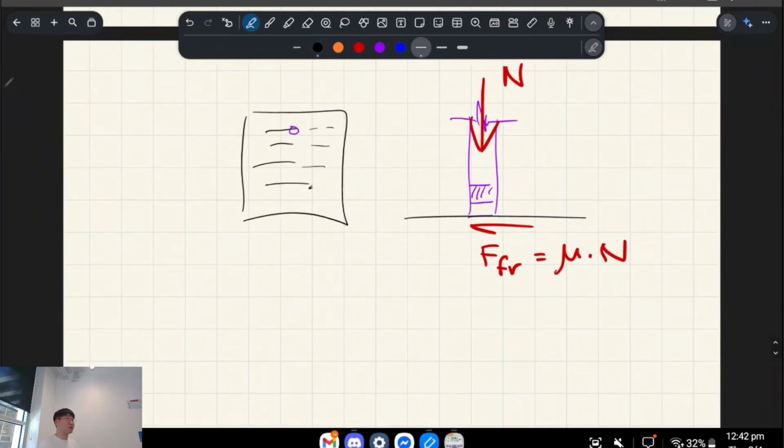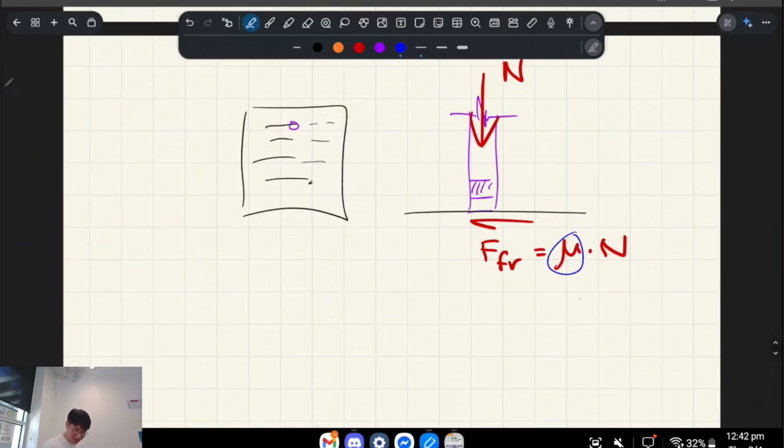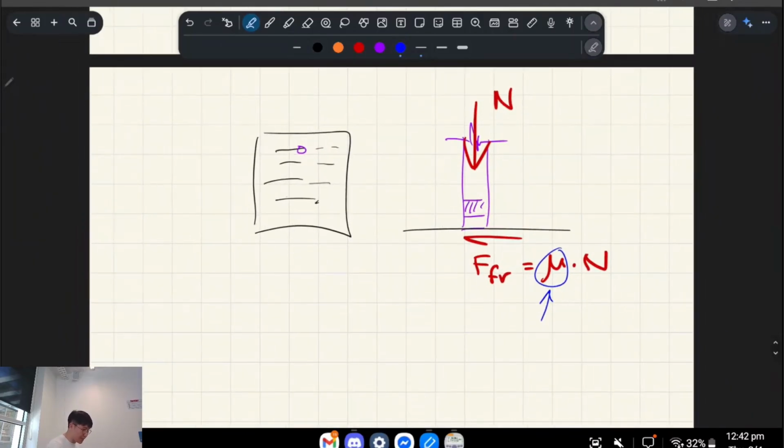So the same concept applies when we're talking about anything that's sliding or is resisting friction, but it's sometimes worded differently. So instead of mu in this case, we're going to be talking about it in terms of tan delta, where delta was 0.6 times the friction angle, where that was 30 degrees.